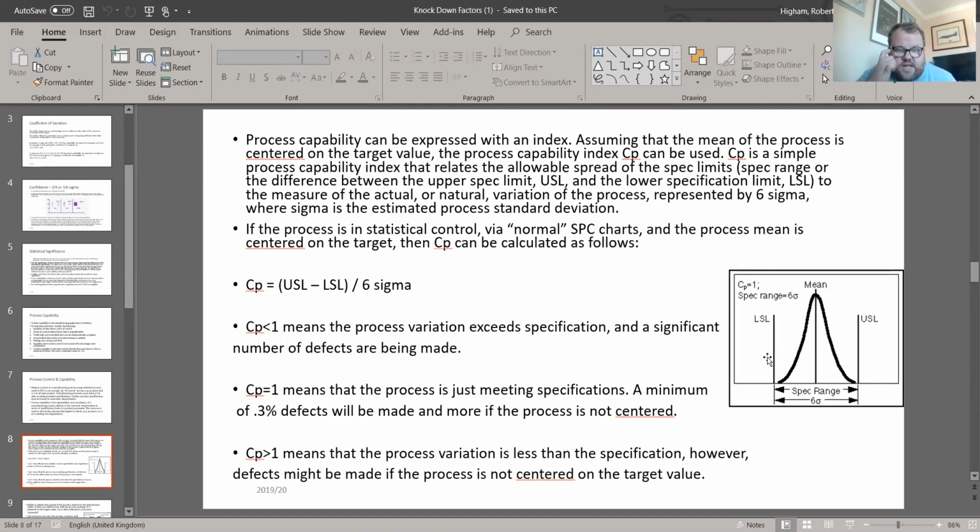And the lower spec limit is set or calculated based on making sure that we can consistently meet that. So it's the mean minus those 3 sigmas. So from the central mean minus 3 sigmas to the lower spec limit. So if we have mean and we have the standard deviation calculation, we can then say the lower spec limit for that data would be blah, as long as you've got the right considerations in that calculation in terms of quantity of test, etc. Quantity of test in particular is really important. That's where this value can come from.